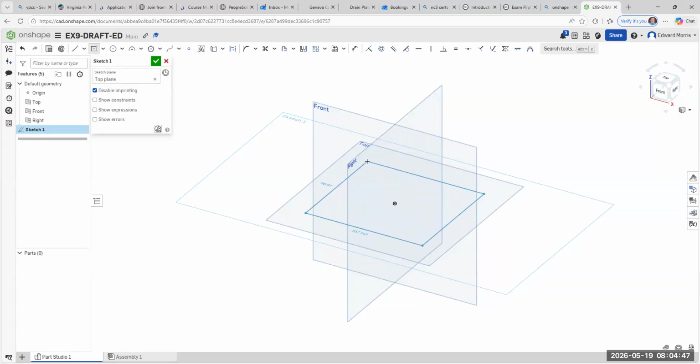We're going to drag this out, and I'm going to click, and I'm going to edit these dimensions. The first dimension I'm going to type in is 50 millimeters, roughly about 2 inches. Enter, and then we'll type in 50 again, and enter. All right. Now, that's a square. Squares are easy to make, right?